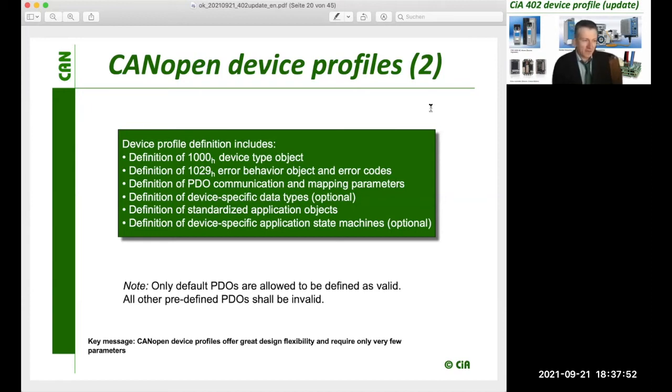So first of all, we have a parameter. As you know from CANopen, there are parameters defined in the CANopen Object Dictionary, and they are defined as references to parts of the memory, and they code indexes, and each index has 255 sub-indexes.